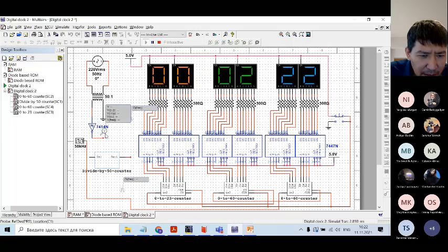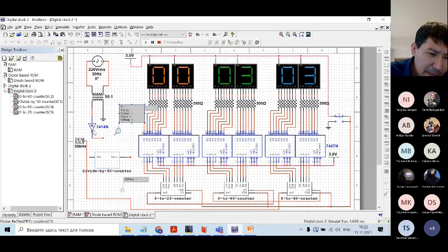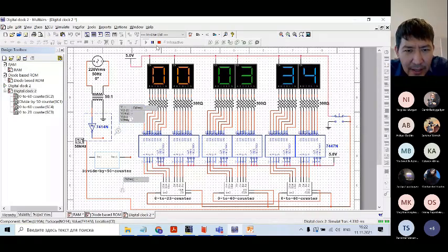But after the Schmitt trigger, for some reason I don't have any. It's not right. Can you see? It is a lack of inverter. I need to use another one. But anyway, I can just skip this part.